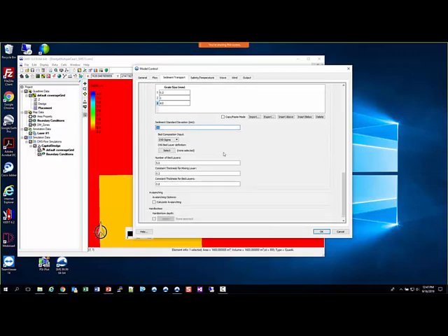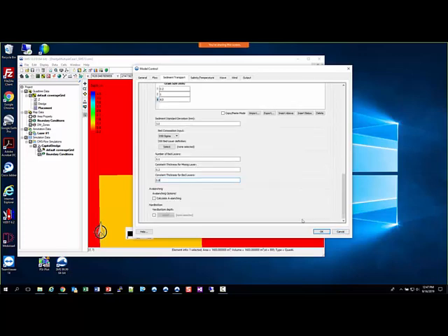Standard deviation, we're going to set to 3. We're using the D50. I've got to come back and do the D50 data set. Bed layers, 5. Constant thickness of 0.2 for the mixing layer and bed layers. And then that's all we need to do there.